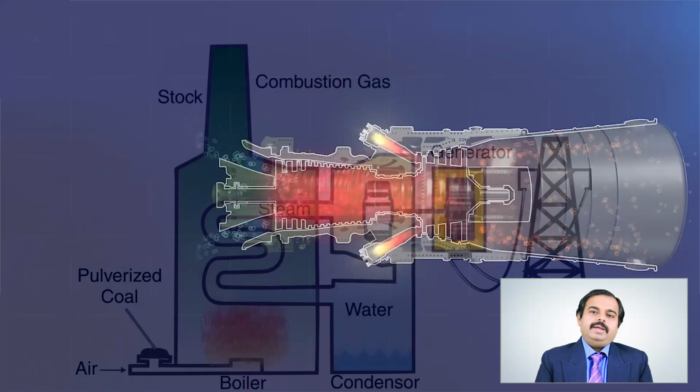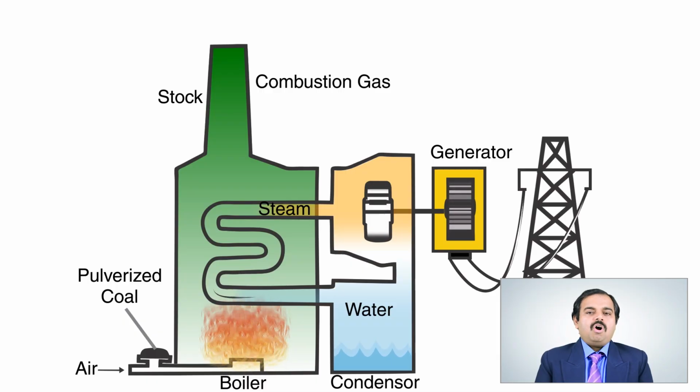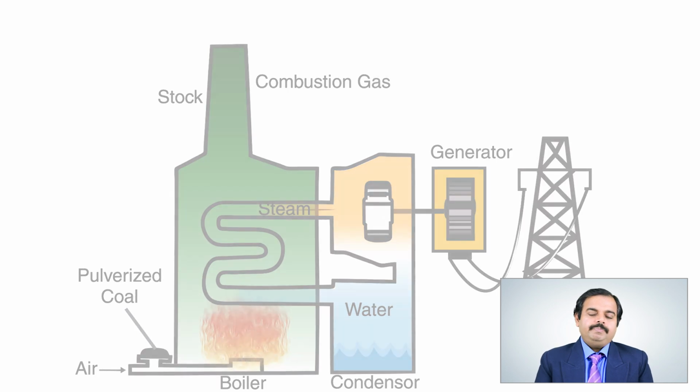In the steam turbine, the oil separates the moving shaft and the stationary bearings. Before the start of the turbine, the pressure is developed to keep the shaft floating. Once the shaft starts rotating, the pressure is developed by hydrodynamic principle.